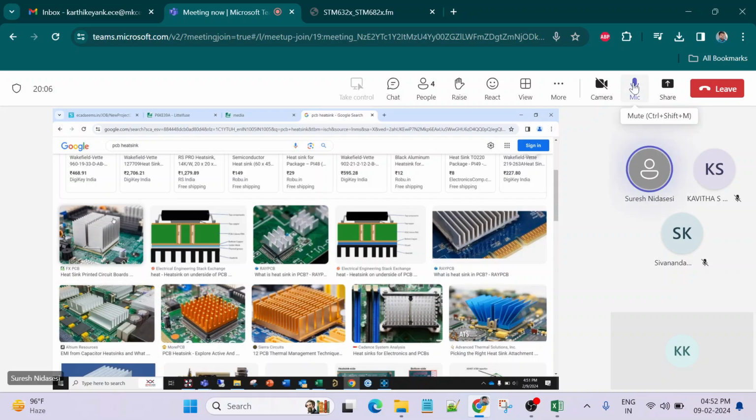This design will be very important at the system level. If you see, this one has three fins on each heat sink, and the number along the X is also more, whereas here there are only two fins. In this itself we can see that for this one they have fixed one common heat sink fin, whereas here they have split it into three. The reason is this will have more wattage than this.